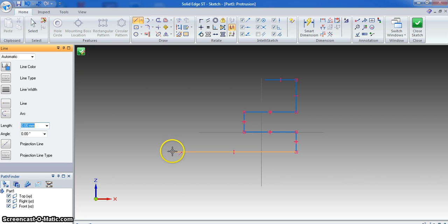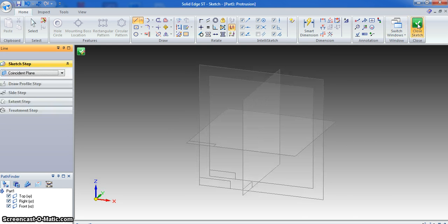You can see that the little icon next to the cursor is that little round point on a stick, so I know I'm coming to the end, going to attach the end of that line. So I just click on the end, and then I'm going to come up 20, enter, and then all I have to do is join one point to the other, and then right click, and I've got my full shape there, and all I need to do is extrude that by 22.